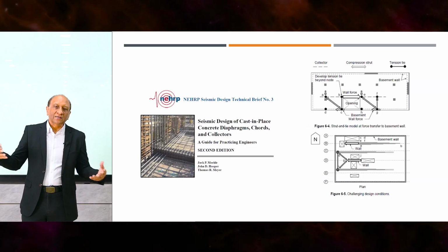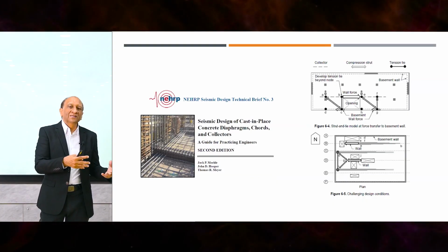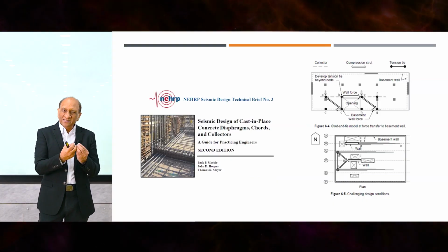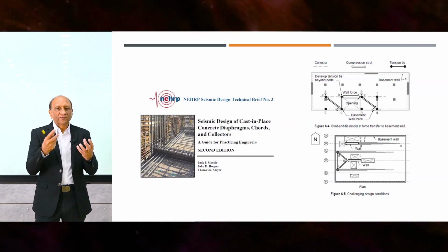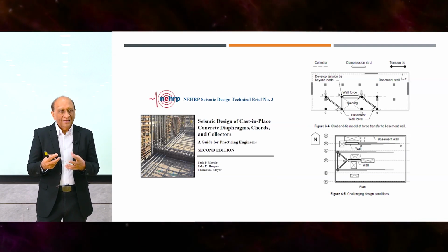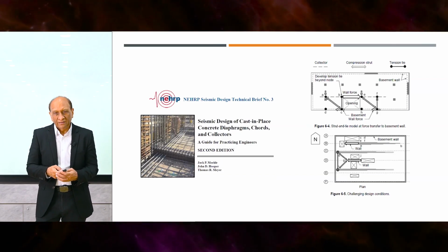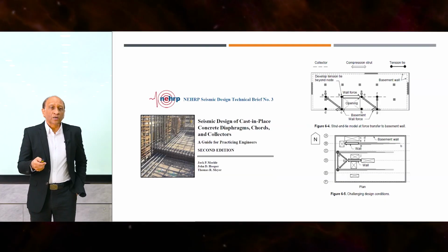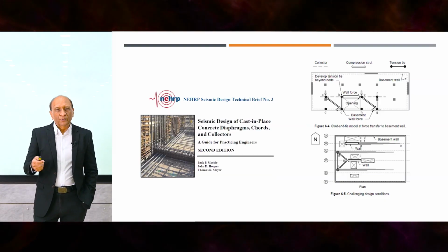The collectors are basically to collect the force or the stresses to the struts and ties, because struts and ties cannot just exist and come out of existence suddenly in a continuum. They need to spread around, and that spread around portion is done by the collectors. So that's how the floor diaphragms can be modeled, multiple ways.